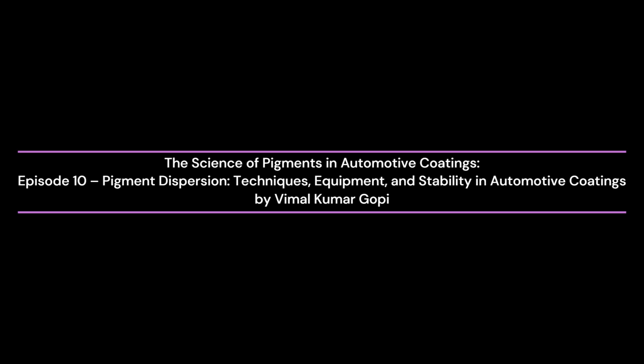In multi-pigment systems, interaction between pigments must also be considered. Agglomeration of one pigment can induce flocculation of others. For example, carbon black may interact with titanium dioxide if dispersants are insufficient or if surface charges are mismatched. Careful selection of dispersants and sequencing of pigment addition is required to avoid instability, color shift, or haze.